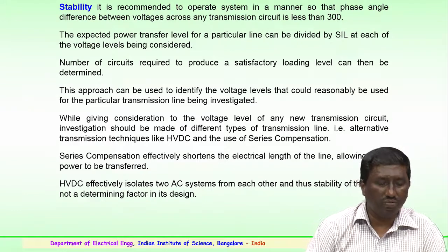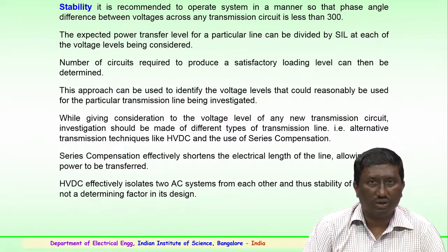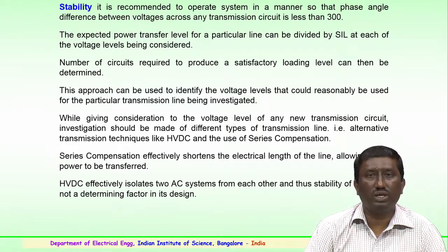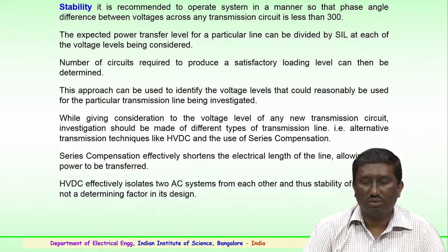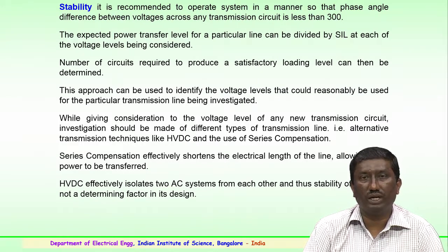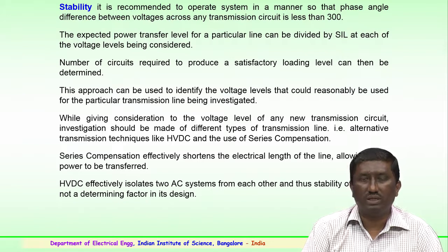The stability is very important for any power studies. So, it is usually recommended to operate the system in a manner so that the phase angle between voltages across any transmission circuit should be less than 30 degrees. That is a very important point to be noted.